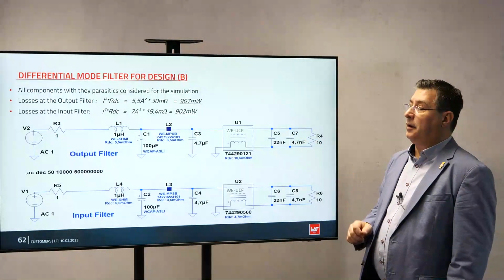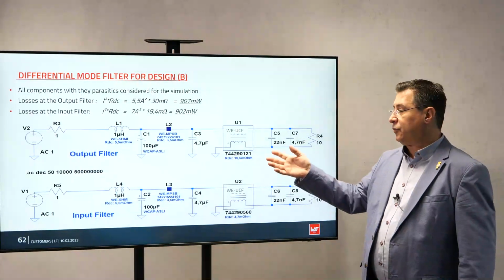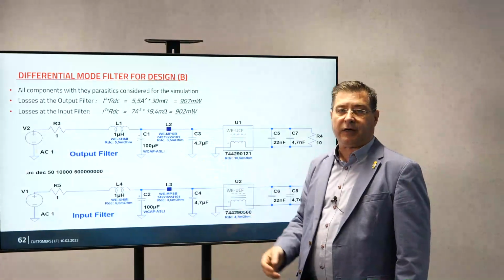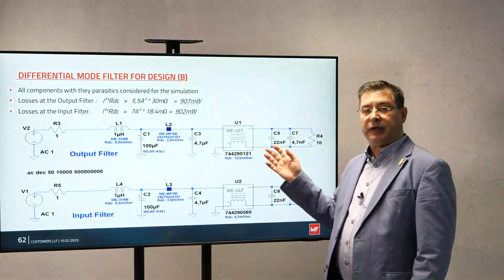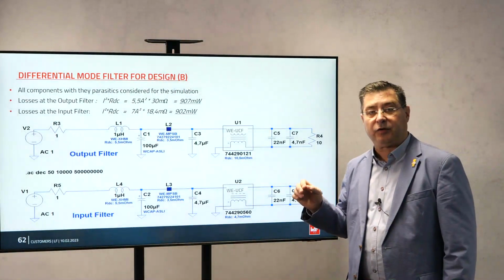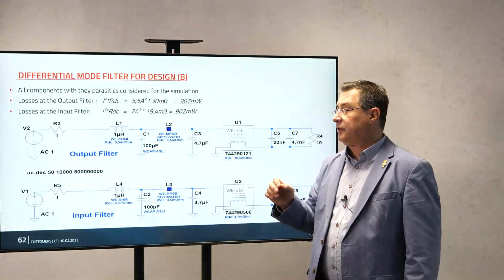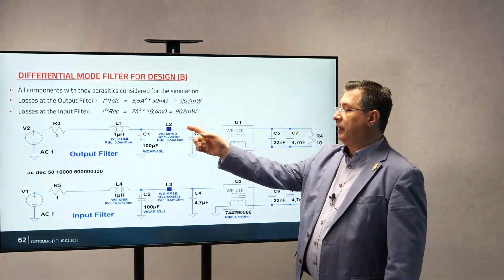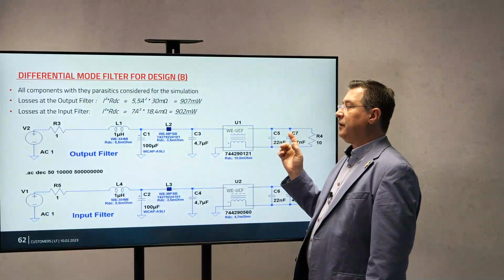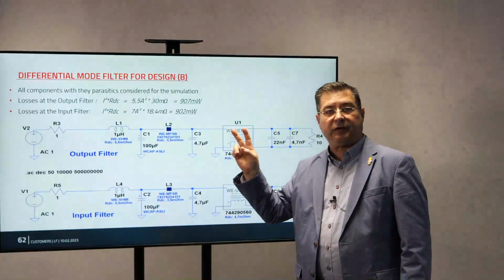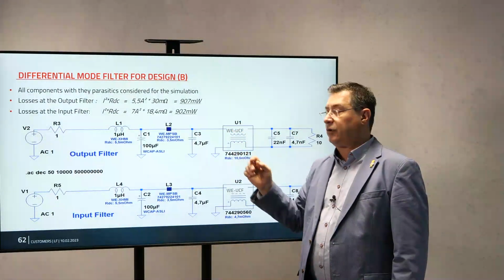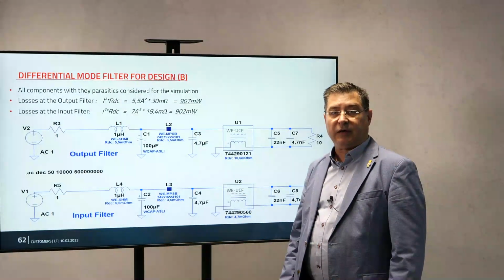Now, in LTspice, you have the models for the common mode choke, for the ferrite beads, for inductance. Already you can simulate that, and you can pre-estimate the losses. At 100 watt, you can really fast see that adding all this resistance together, you may have already 2% losses only on the filter. 1 watt and 1 watt from 100 is already 2%.